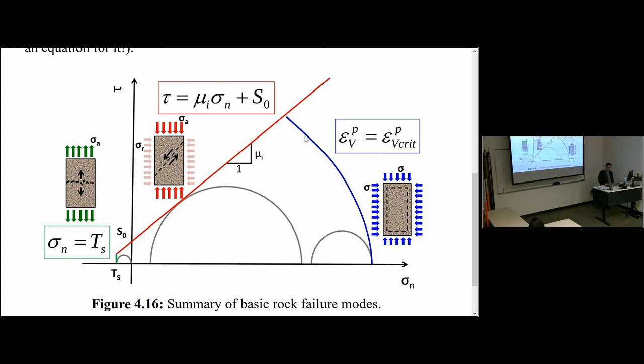And what that means is that in this region you have something which is called shear-enhanced compaction, which is compaction but also with the help of shear. Both of them are acting to break the rocks and to break the grains, and actually that makes it easier. With a little bit of shear, you can make the failure happen earlier than if you just had pure compression.